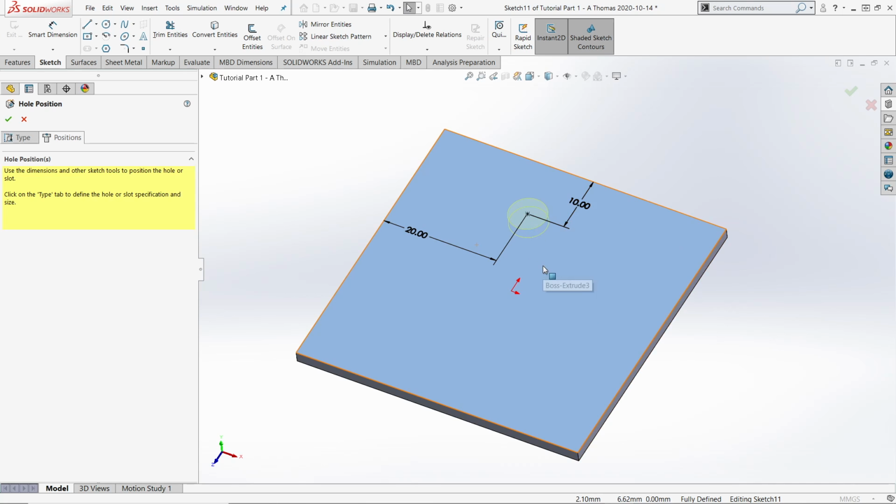So if I made this plate and I gave it to the shop and I told them, hey Alex, I want this hole to be like 5 centimeters from the center in the x-axis and 10 centimeters from the center in the y-axis, he would get annoyed because he would then have to find the center, right? And depending on how the plate is manufactured, that center might be different than where it is in CAD.